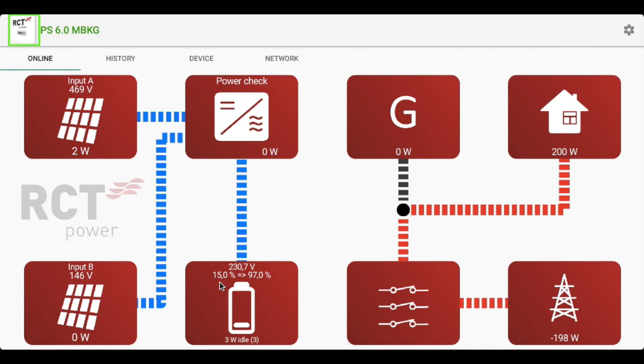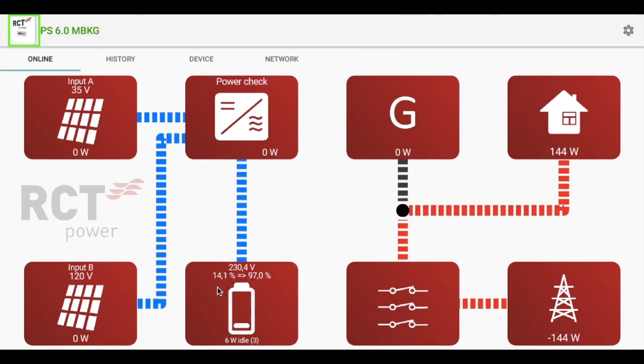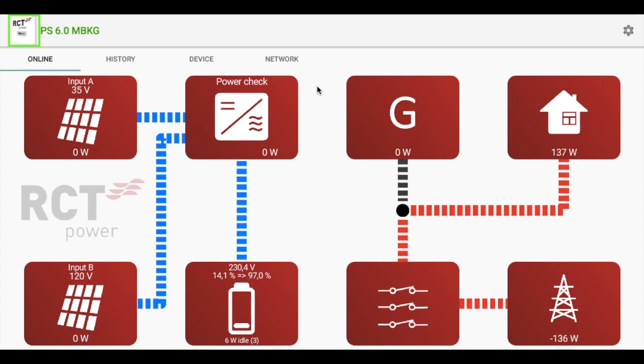So we have 10% as the buffer in battery to run the system in island mode in case of power outage. So when battery is fully discharged, inverter will disconnect the PV system from the house. So our consumption is fully covered by the grid.